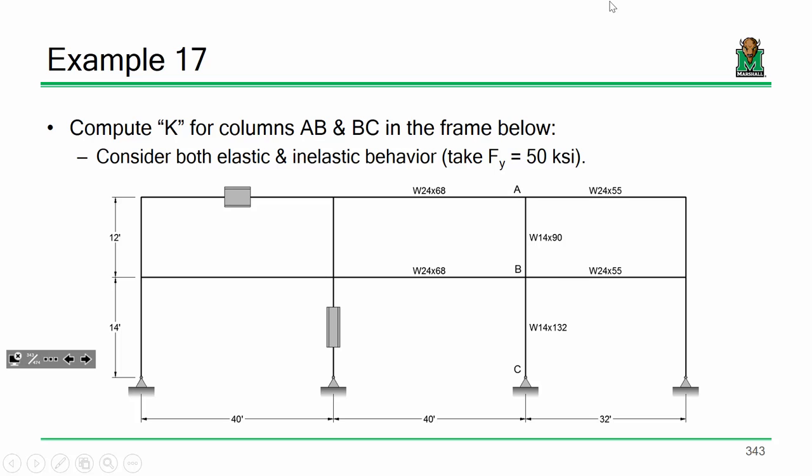Now, residual stresses tend to affect a column's capacity more in the inelastic range. It tends to increase your likelihood for inelastic buckling. Sound good? Here's my point. You do get a benefit from using tau, so I understand what you're saying, that erring on the side of caution would mean not using tau. However, by not using tau, we're also not recognizing reality. Those alignment charts, just like the derivation of Euler buckling, assumed that the behavior was elastic. And I think we know by now that that's not the case.